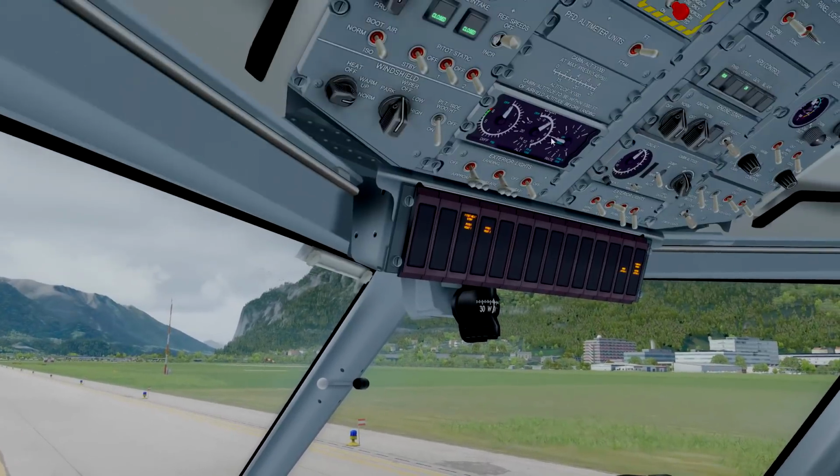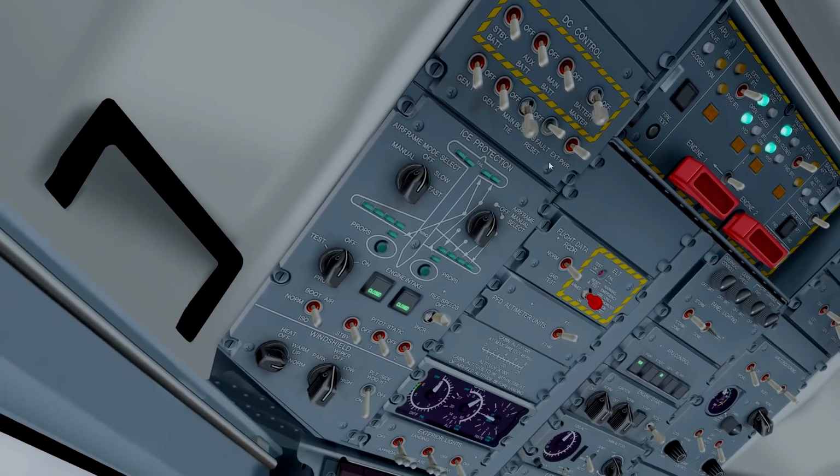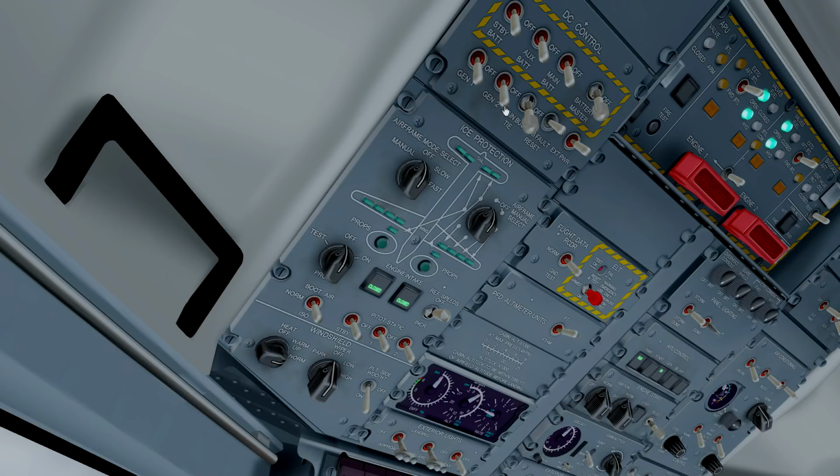Okay, so now we'll just go through the overhead panel. So we'll now just run through this column by column, make sure that everything is set, all the batteries are on as set. Basically the generators have to be on, of course, and we can turn off the bus tie. There we go, and make sure that the generators are on before you disconnect the APU. You just really want to make sure that the engines now supply the electrical power to the airplane.